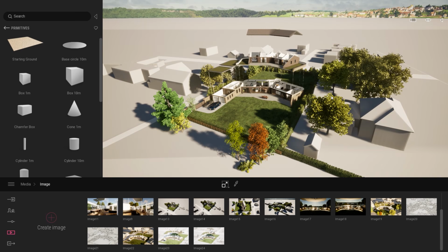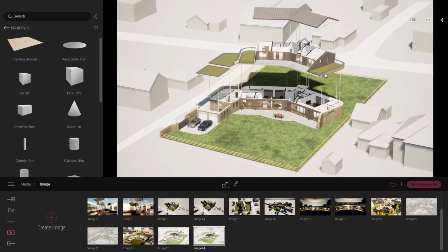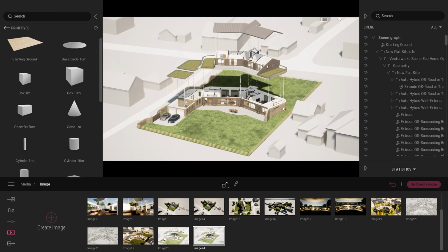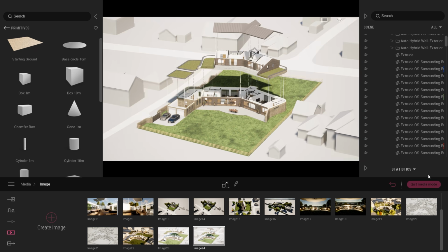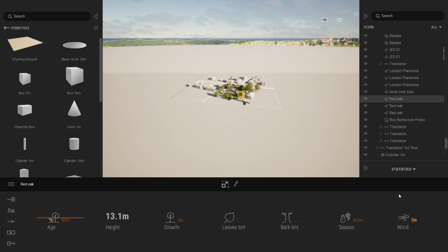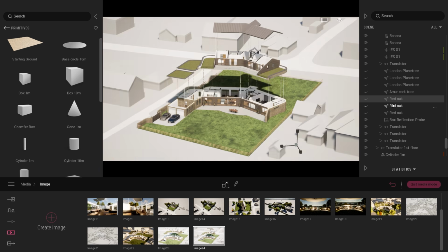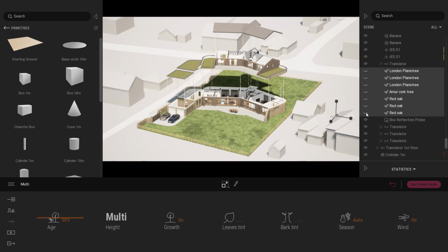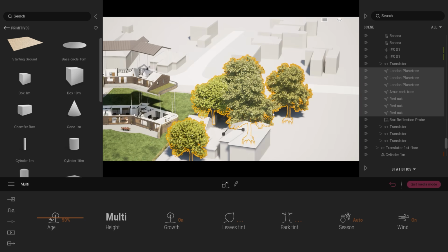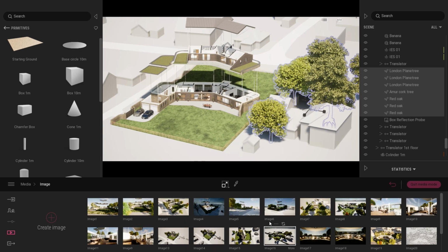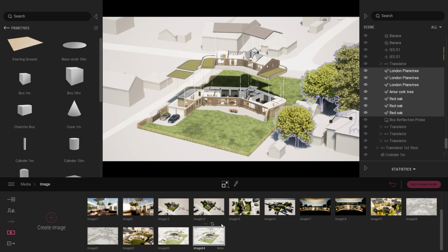Then the next step was to hide the vegetation. I still wanted to keep them in case I need them for another view, but in my specific view I didn't want any vegetation. So I took all my tree assets. Let me actually just select one so I can see where it is. Let me come back to my image. I simply selected my trees. And while they were selected, inside my viewport, I clicked on the little refresh button to memorize the state hide and unhide of the object on this specific view.